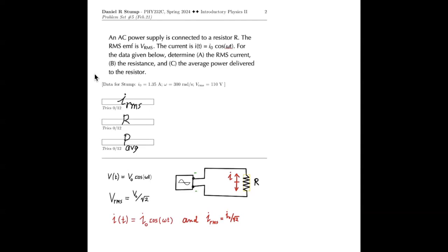You're supposed to calculate, well, what you're given is the root mean square voltage. The average voltage is 0 because it's alternating between plus and minus, plus, minus, plus, minus. You take the average as just 0. But if you square it and take the average of that and take the square root, that's the RMS. And it's 110 volts, like you would have in a wall socket.